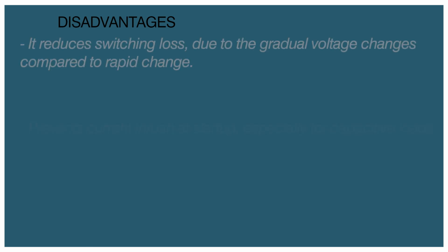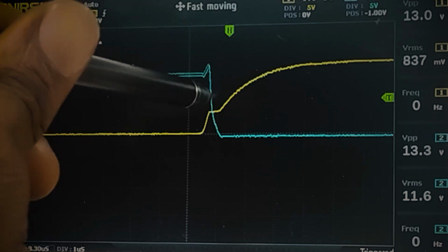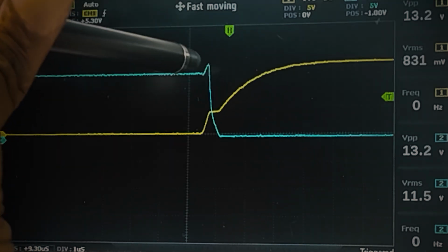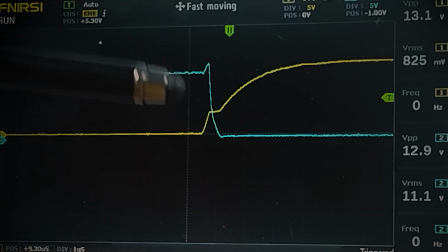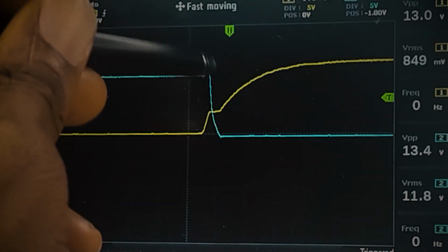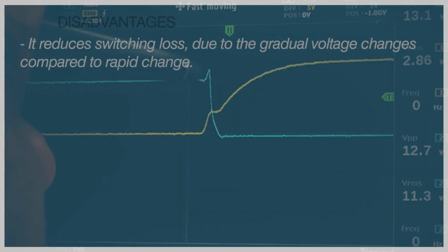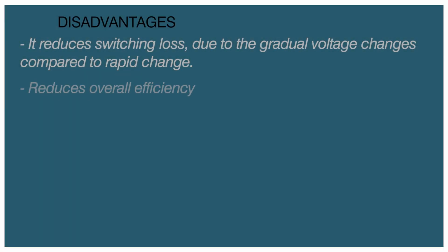Of course we now know the advantages of a slow ramp, so I will still start by mentioning losses. For disadvantages, if your ramp is not steep enough, the MOSFET will spend more time in the linear region. And remember, in the linear region we mean the region where your MOSFET is not fully on or fully off. So the gate to source acts like a resistor between them, and they definitely dissipate heat. And so the MOSFET is not expected to stay in the linear region for too long when it's used as a switch, because it reduces the overall efficiency, because you have more power wasted.